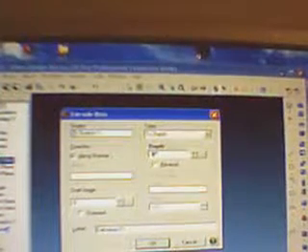Okay, next we're going to go over to the extrude boss, top right hand corner from the modeling toolbar. Once we've clicked that, this window opens up. This area says sketch 1. I want to click there. That's where we're working. Here I highlight this. I'm going to make this 0.8.